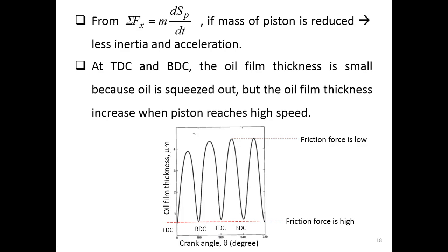Another reason is that at these positions, whether bottom dead center or top dead center, the piston starts to change its direction. So the oil film thickness becomes small. But at other positions along the way that the piston moves, the oil film thickness is always higher than this, and it can be increasing or decreasing.